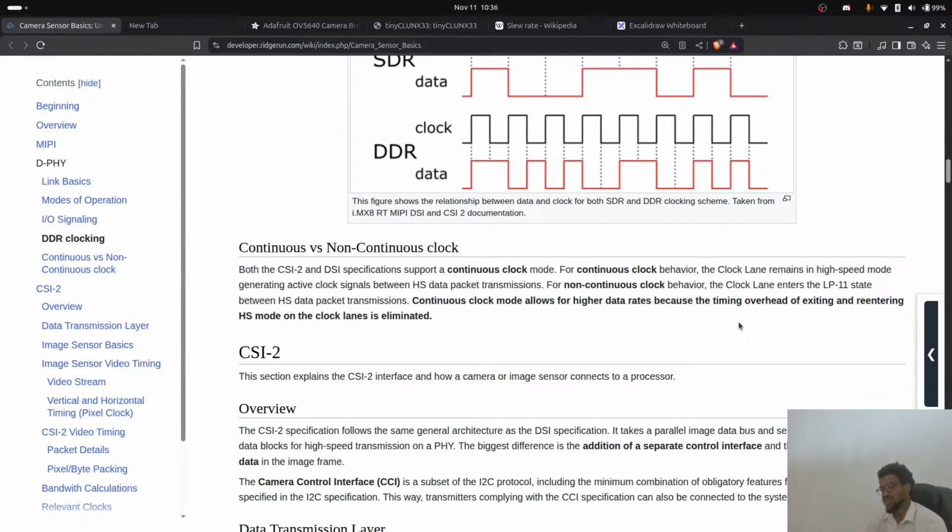So basically, because you're not using time switching clock modes, the clock is always there. Whenever you're not transferring data, the clock is still going in high-speed mode, and you don't have to wait for the rise time and fall time to be able to do this stuff. And so at the expense of power consumption and budget, continuous clock mode actually does perform way better in sampling stuff.